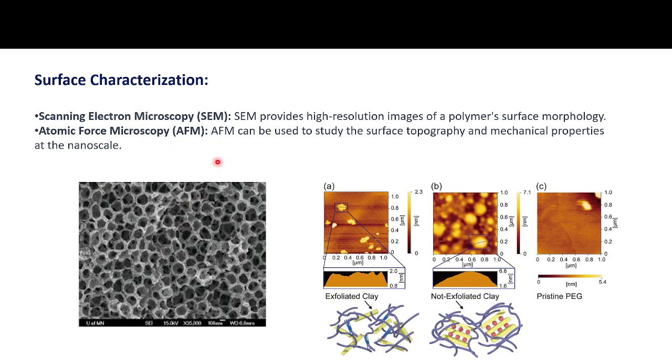Why are these techniques important? If we have prepared a nanocomposite material, and the nanocomposite is not aggregated but distributed over the surface, then the total load bearing capacity will be higher. If it aggregates in some regions, and other regions have no nanocomposite, then the load bearing capacity of the overall material will not be so high. Nanocomposites have applications in aerospace engineering, where we can get lower weight materials with high load bearing capacity, high toughness and high strength.